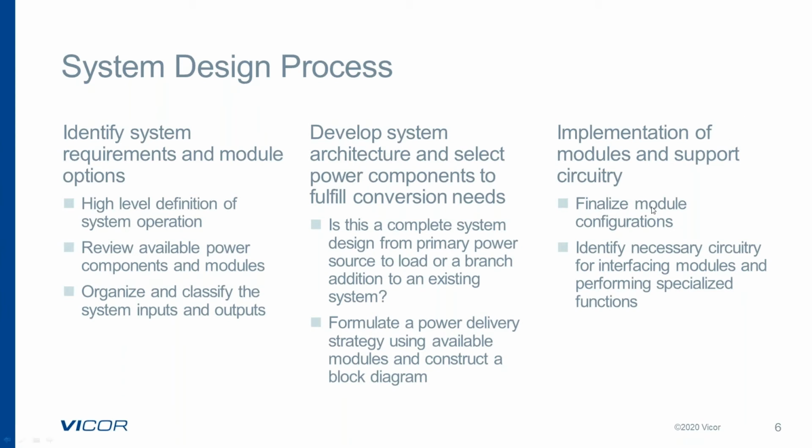And then lastly, consider the support circuitry needed to finalize the power system. This is where your EMI filtering would come into play, as well as special needs for the system, whether it be output voltage sequencing or hold-up requirements. That's the next step.